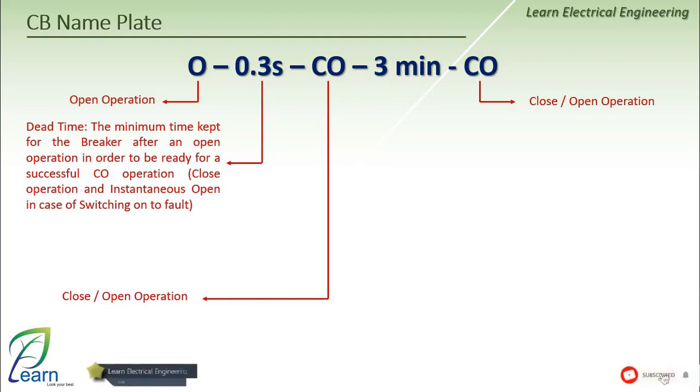What does this mean? We all know that overhead transmission lines are highly exposed to transient faults, which is why we activate a function called auto reclosure within the protection relay. The idea is quite simple. When a fault occurs on the overhead line, the protection system will issue a command to the circuit breaker to open. This is considered an opportunity for the fault to clear. But suppose the fault still exists, meaning the fault is still present on the line.